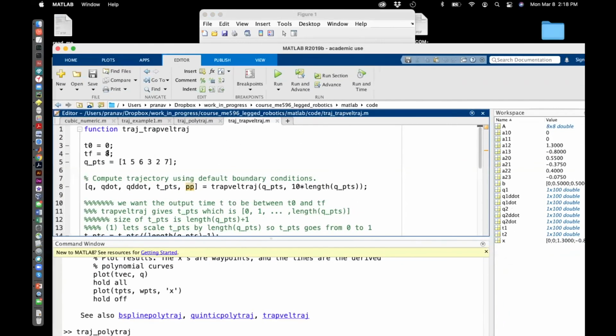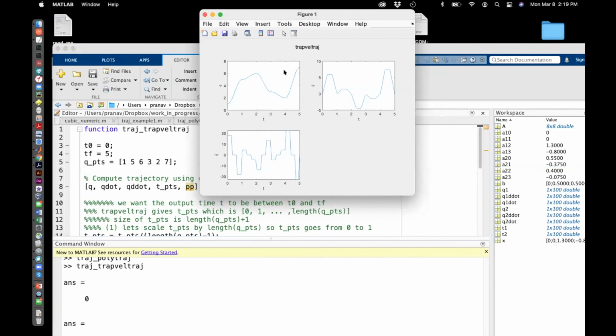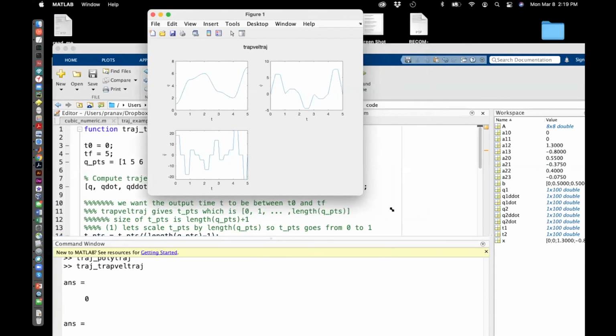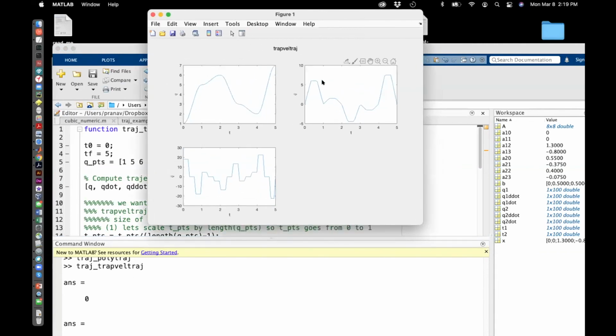Okay, so I'm going to change this back to 5. That's easier. And now you will see that it actually uses constant velocity profiles. So what changed was the velocity is capped. It's capped here. You can see the acceleration is no longer, well, sorry, my bad, the acceleration is constant. And so it basically caps off the velocity. It doesn't let the peaks come.